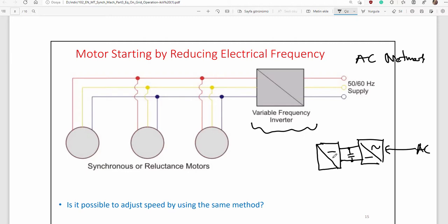And then that DC will be converted into a new synthesized three-phase AC. Here you see the voltage output, let's say V new and f new, will be synthesized here inside the new power electronic device you have introduced to the system.